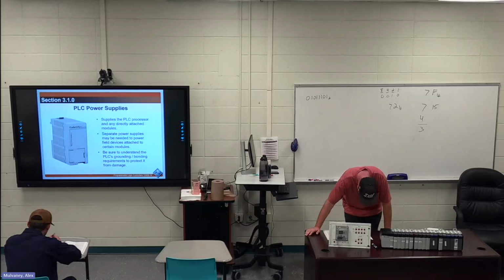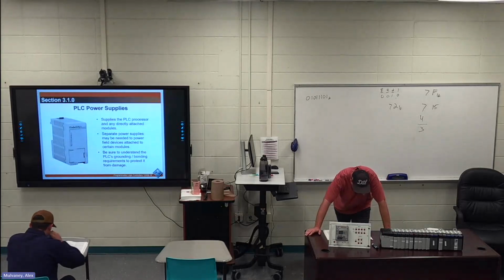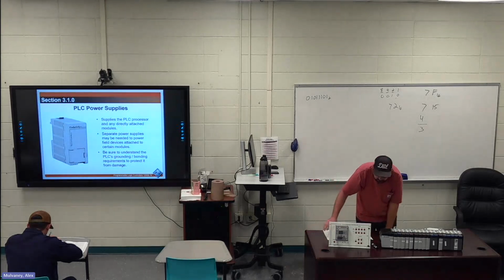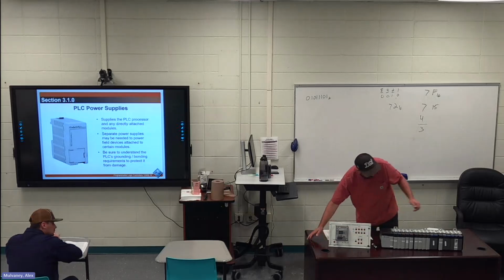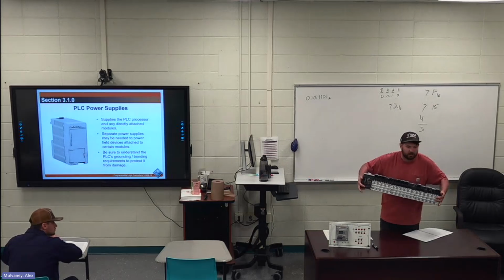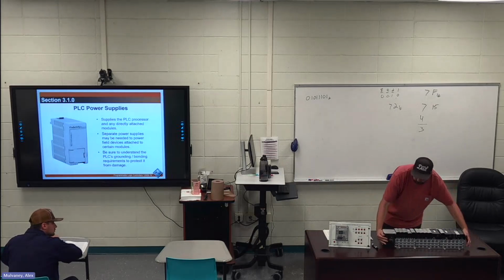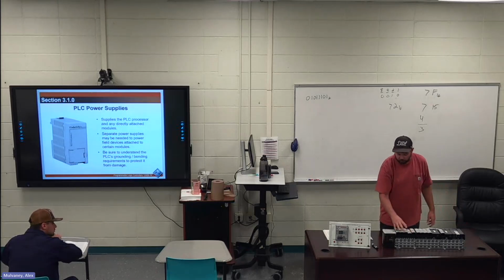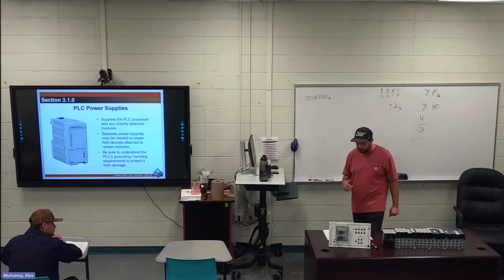The next two sentences are highlighted. Static discharges from improper handling can destroy them. Static discharges are stray voltages from process equipment, processes, or non-process activities such as welding, and they can destroy electronic devices if they're not properly grounded or shielded. All of these PLCs will have a ground; this has to be tied to the ground. You can see where it was cut off, these have to be grounded. These modules are $5,000 a piece, new. You don't want to fry every single thing in this expensive stuff. Even static discharge is not good for this.